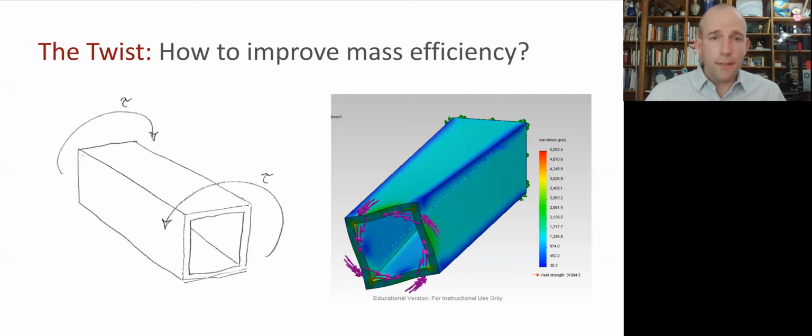And please hit pause now. All right, so presumably what you noticed is, again, we have this uneven pattern of stress, although now the distribution is more complicated. We see that there are these blue regions on the outer corners of the cross-section. And there are much higher stresses along these sharp internal corners and also in the middle of those faces. And perhaps you thought about ways to reduce those stress concentrations and remove some of that outer material.